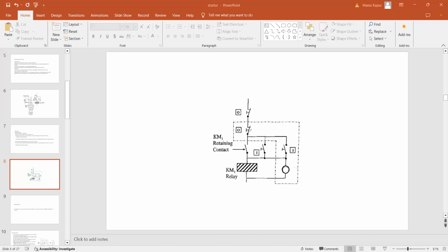But if something is wrong at the stop, you will not be able to start the motor, because stopping is still acceptable, but starting a machinery without knowing the actual condition is dangerous, right? That is why, instead of putting the stop switch in parallel, they put them in series. They could also put a stop switch here for the remote operation if they wanted, but they are not putting it like that. They are putting it in series. Understood the difference? Rest all working is the same.